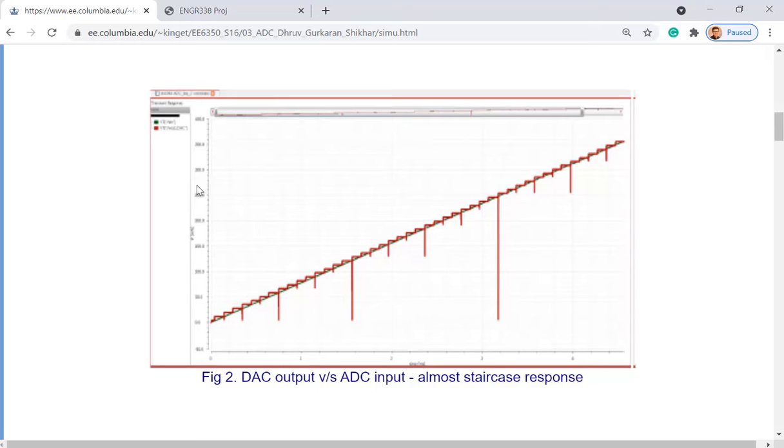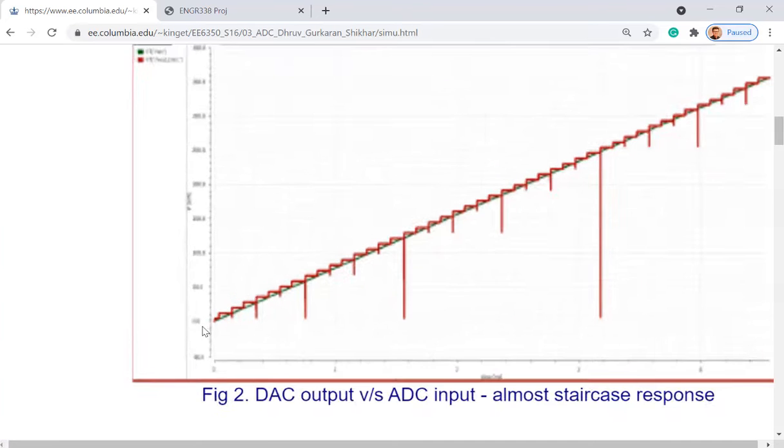You couldn't modify it. You extract the data and then save it in either .txt form or .dat form or any type of text or data file and load it into MATLAB and do the calculation so you can get all the points, right? So you can find out all the points. It's just like a matrix, but it's one dimension, like a vector. And you need to know what are the points you want to use to calculate DNL and INL. What are these, for example?